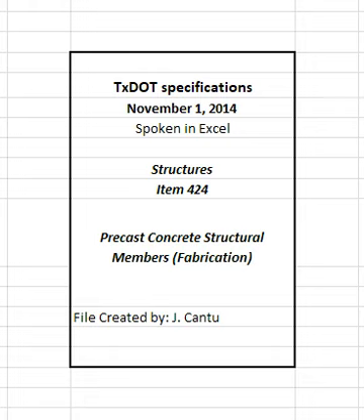4650, hydraulic cement concrete curing materials and evaporation retardants, is also acceptable if used in accordance with the manufacturer's recommendations. Do not apply the evaporation retardant when floating and troweling concrete. Do not allow it to puddle or be worked into the concrete surface immediately after application. Misuse of fog spray or evaporation retardant will be cause for disallowing its use.